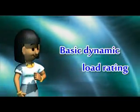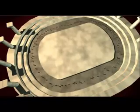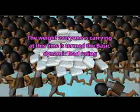Basic dynamic load rating. What is the basic dynamic load rating? Let's use an example to explain this concept. Suppose 100 runners are carrying heavy objects in a marathon, and they run 1 million laps around the track at the same speed. In this marathon, at least 90 athletes must complete the full race, and fewer than 10 persons can drop out. The weight that everyone is carrying is termed the basic dynamic load rating.